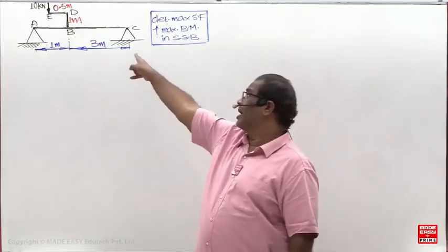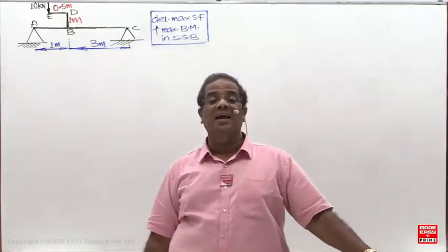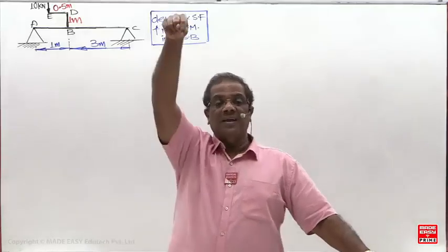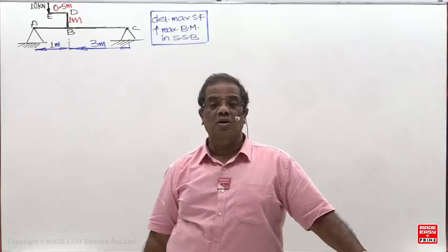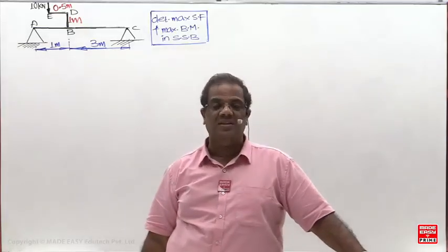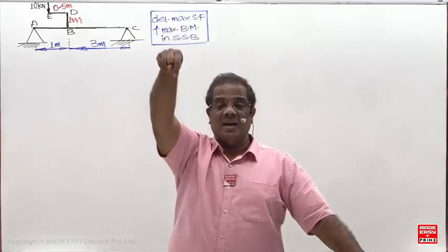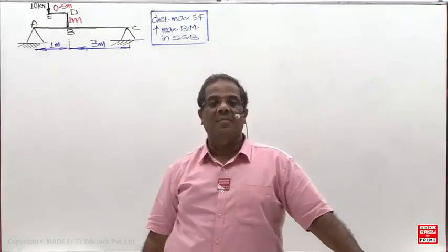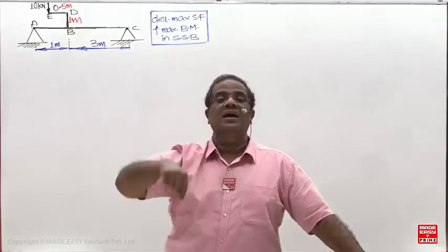Now, directly, a bracket is welded above, and a load is applied at the end of the bracket in the vertical direction. Either you can use two dummy forces or directly use what you have studied: when the load is applied in the vertical direction at the end of the bracket, it is equal to one constant point load in the same direction and a couple.